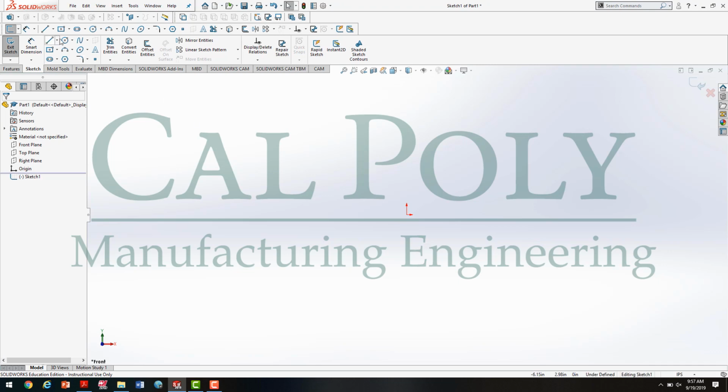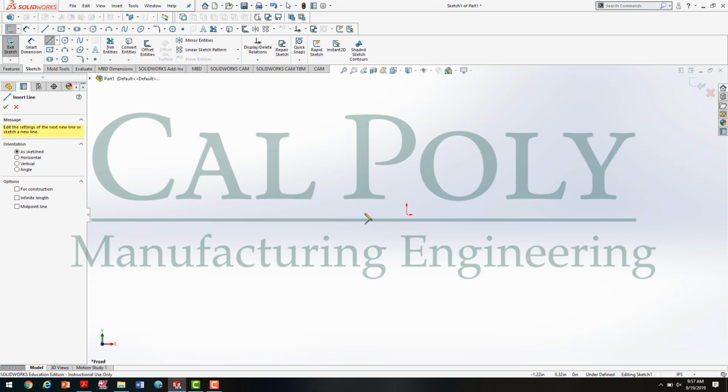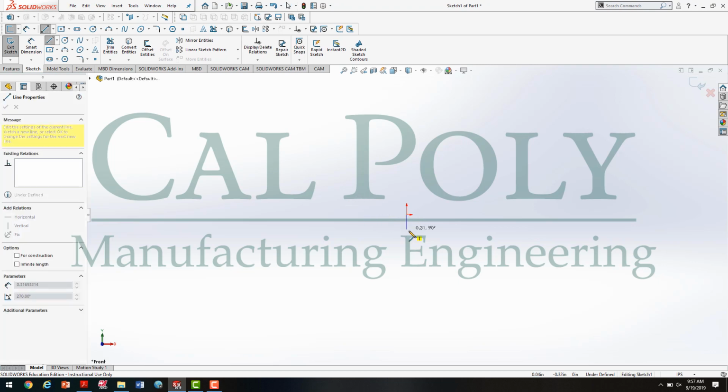So what I'm going to do is start off with my line tool. I'm going to draw the overall shape by clicking my left mouse button once and dragging down the line. If you notice, the little yellow icon is signifying a vertical relationship. If I move off from the vertical point, that icon goes away and my line will no longer be vertical. So I want to make sure I create a vertical line. I move over, make a horizontal line, another vertical line, and also notice I'm not actually sizing it at this point. I'm just drawing it very close to the final dimensions.